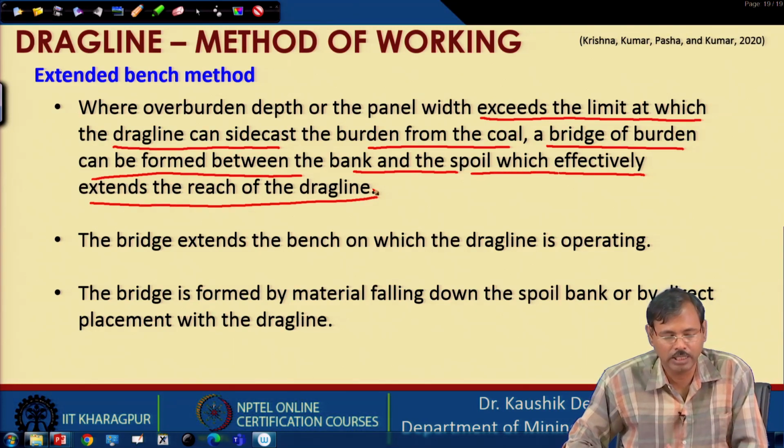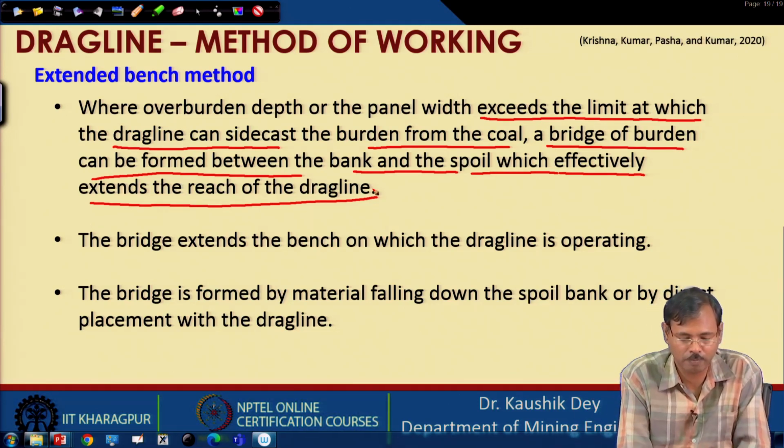So, basically the extended bench method is allowed where a dragline standing on the bench cannot have the reach to transfer the material. So, the blasted muck pile is utilized to extend the bench, and in this way we are extending the reach of the dragline.